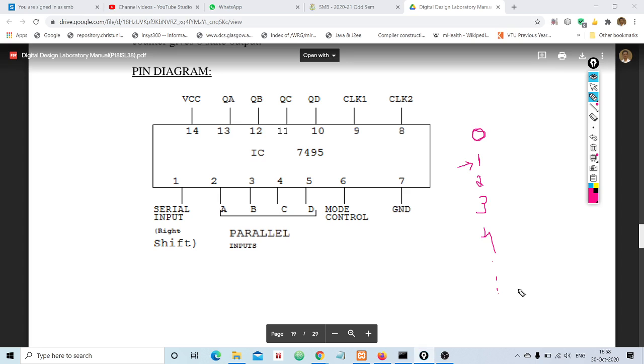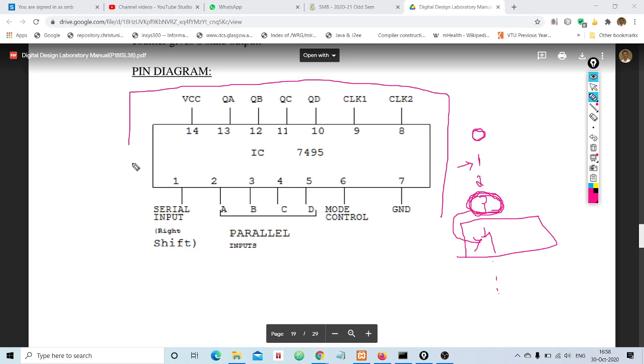So the interesting thing here is, if the counter has to go to the next state, it should be aware of the previous state, right? Means there should be a mechanism inside the counter to store the present state. Then only it can go to the next state. So for exactly the same purpose, to design any type of counter, you can go ahead with a memory element. Depending on the requirement, you may choose a 4-bit shift register to design the counters, clear?